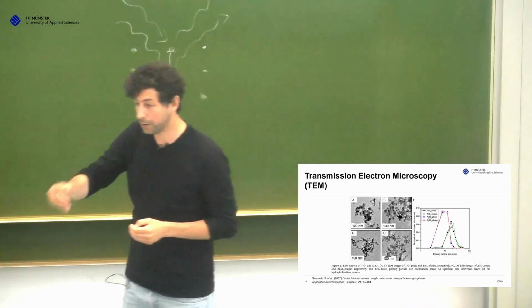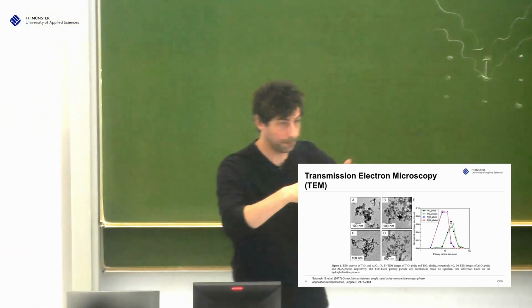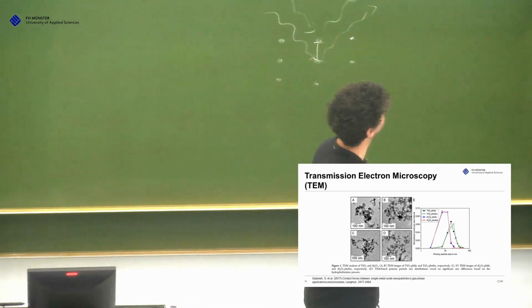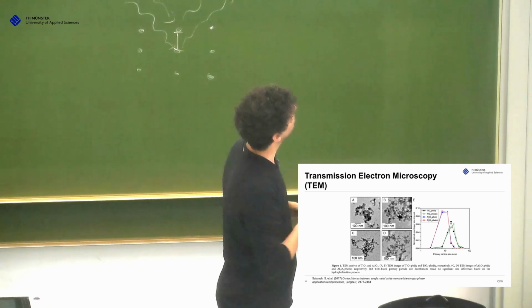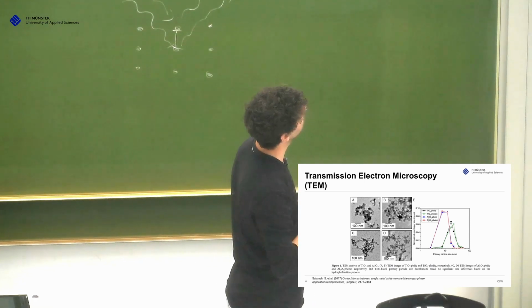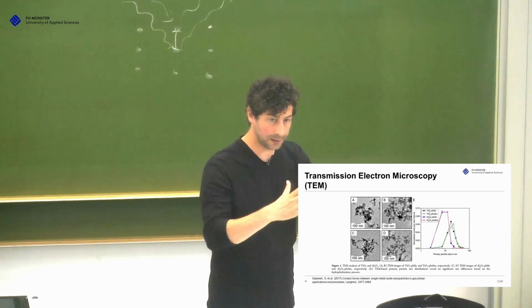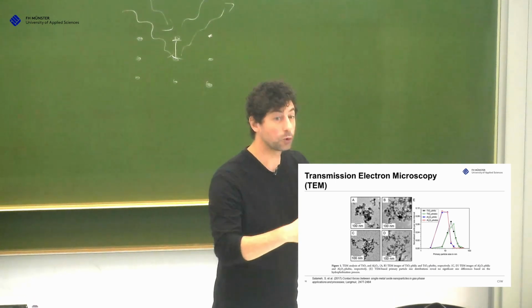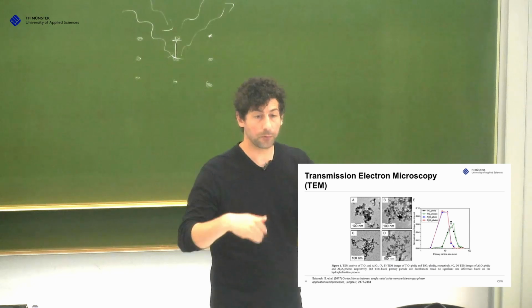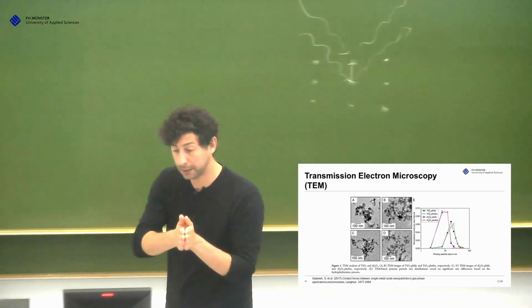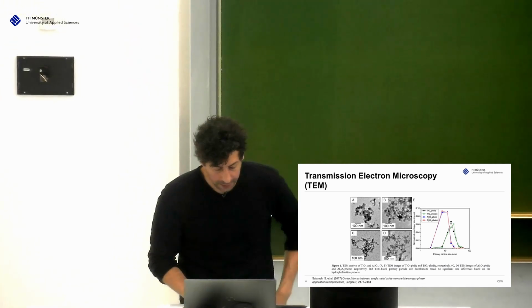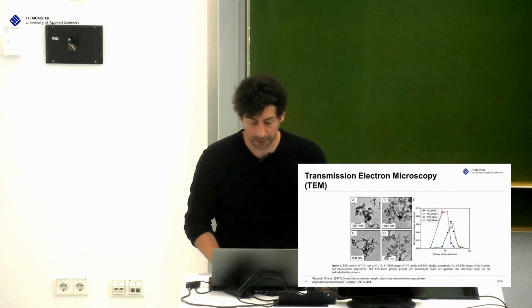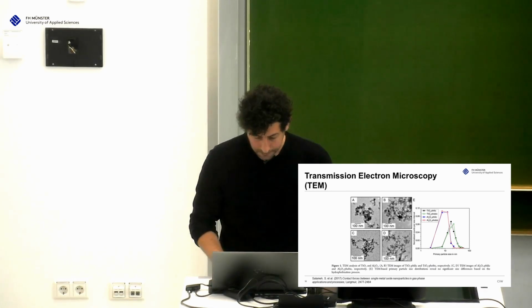So if I change the surface of the particle, I have to be sure that I don't change the particle itself. And this is why I use TEM here, because I want to know the difference between alumina and titania, of course. But it's really hard if I measure different forces between alumina and titania. It could be the size, it could be the material. And therefore, it was really important for me that if I compare hydrophilic alumina to hydrophobic alumina, to show the size is the same. For alumina, it's perfect. For titania, it's more or less perfect, but this is just measurement spread, so this difference is not really large.